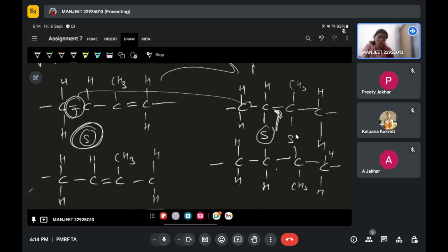So once we do the cross linking, the hardness increases with time as we do the vulcanization. There is the addition of S here that links both the chains, both these isoprene molecules, and this sulfur also links the other two.